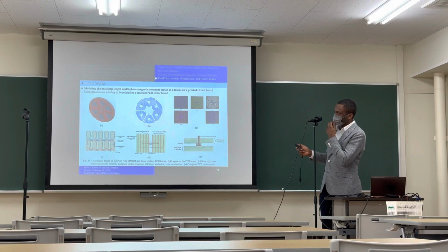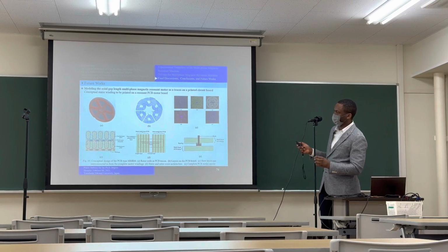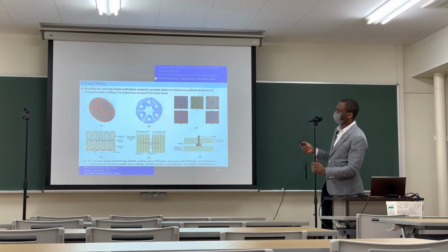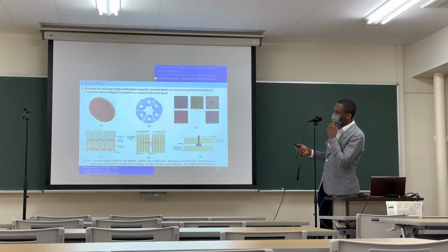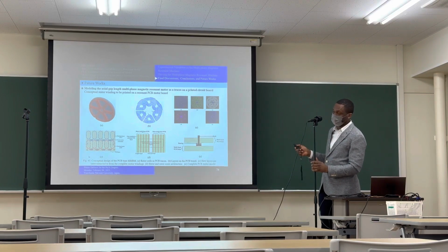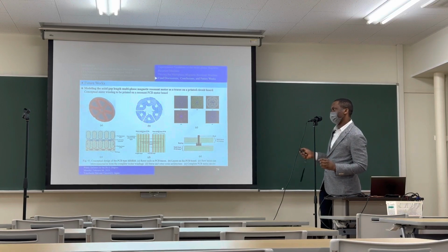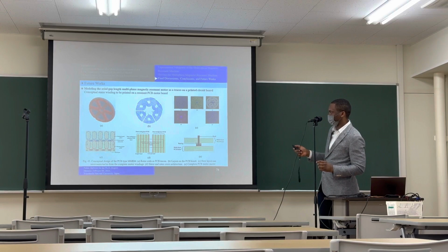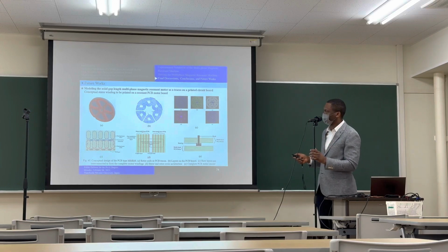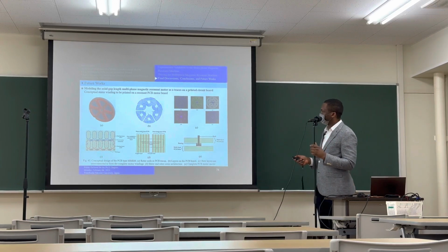And this is the idea of how we are going to interconnect. This is going to be layer 1, let's say layer 1, layer 2, and then we're going to interconnect the layers of different pole pairs. So it's going to be interlayer. Let's say if we have phase A in this layer, the next layer is going to be phase B, and then only the 10th layer is going to be phase A again. So it is some sort of sandwiching of interlayers, and the model is going to look something like this, and then the final design should be something like this, that will have 2 layers. We have a bearing, and then we have some sort of shaft that is going to be attached to the part of the rotor, and something like this. So this is for future work and further work, which can be perspective for other research avenues.